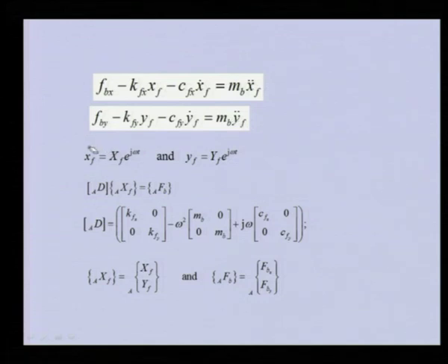Now, again we can write the displacements of the bearing mass in terms of amplitude, phase and harmonic components. We can convert these equations into the frequency domain, and they can be clubbed like this. So, you can see this is the bearing mass displacement D matrix, which will contain these coefficients, and even the mass is defined like this.